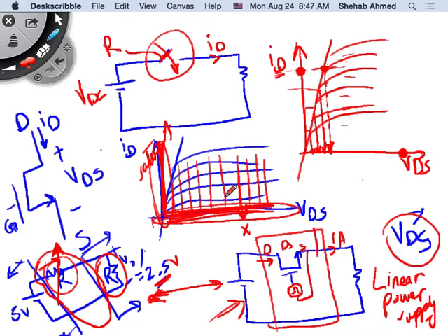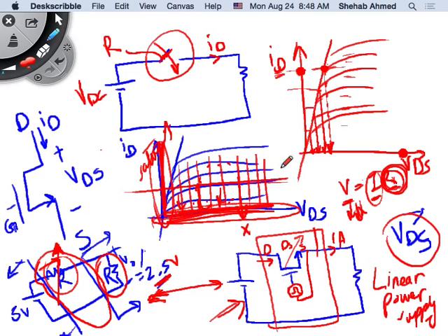Here, I had the same thing, right? But I had many. At every value of current, I had several relationships between current and voltage. So in that case, my relationship is V equals IR. I had a single value of current, for example, and many different values of voltage that it can correspond to. Meaning, did I have a single value of resistance? No, we had a variable resistance. That's how we did this funky transfer, that's how we did this control over the output voltage. We made this look like a variable resistance, right? So we had many values of resistance for the device.